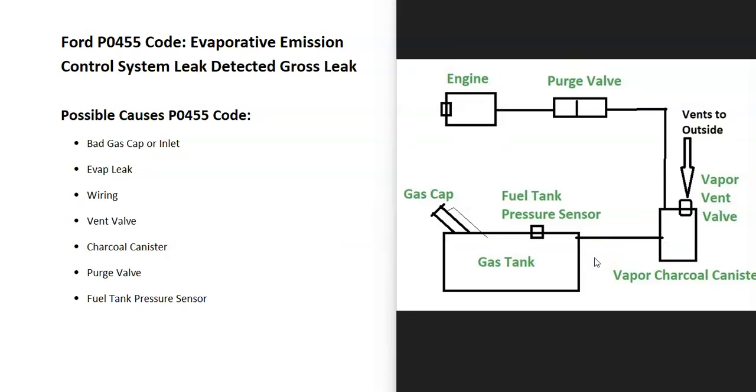Well, modern vehicles have what's called an Evap system that basically takes all the gas vapors from the gas tank and then feeds them back into the engine to get burnt off so they don't escape into the atmosphere. This is for emissions. And the onboard computer is seeing a problem inside the system, mainly a leak, and so it's going to have to be troubleshooted to know why.